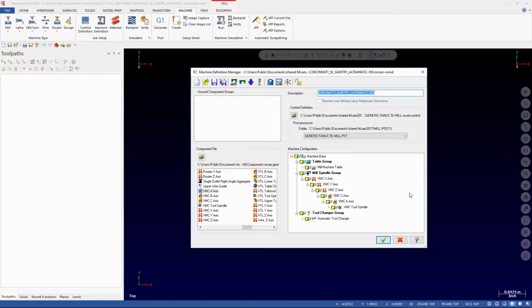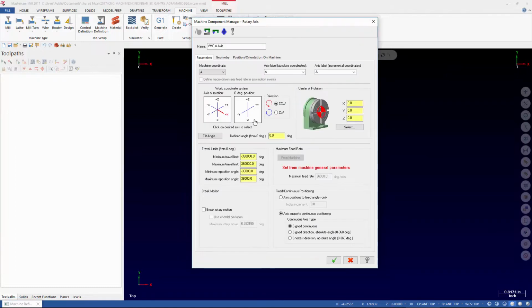In terms of setting up a 5-axis post, once you know what you're doing, the basic configuration is like 10 minutes. Seriously. Now, there's a lot of stuff, don't get me wrong. There's a lot of stuff that isn't supported by default that you might want to add: G10 lines, G68.2 support. The default structure is there, but none of the logic is configured. So there is a ton of stuff that would take you hours or days or weeks to configure, but a basic configuration inside the post is not one of those things. It's super easy. So let's get to that.